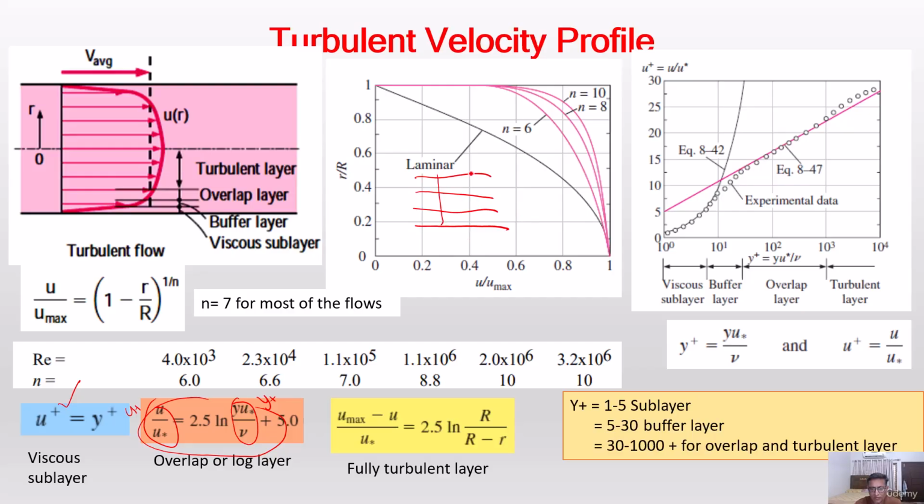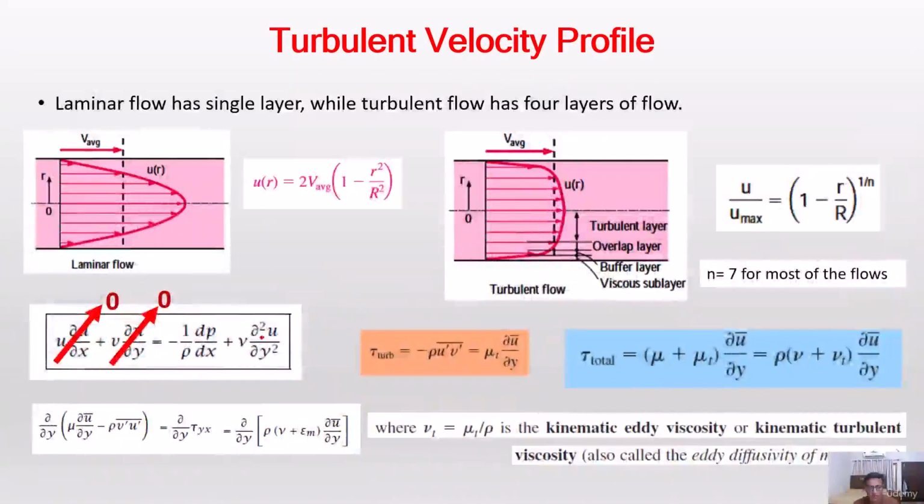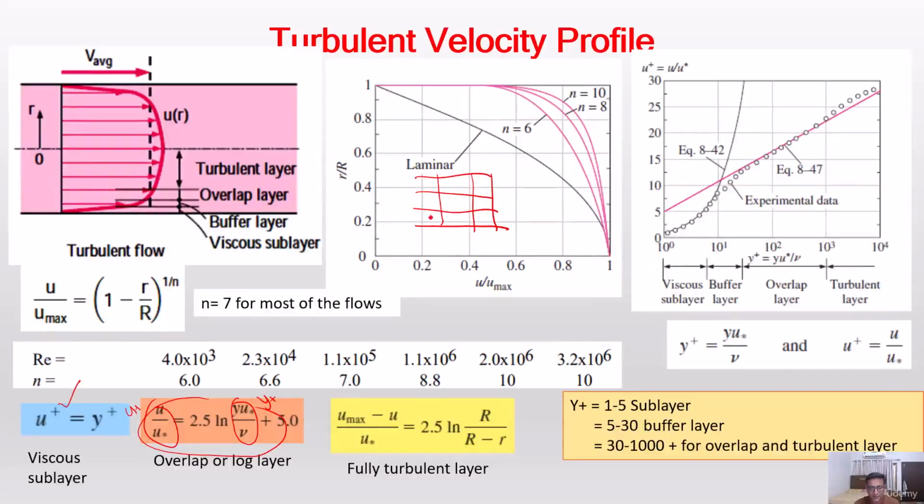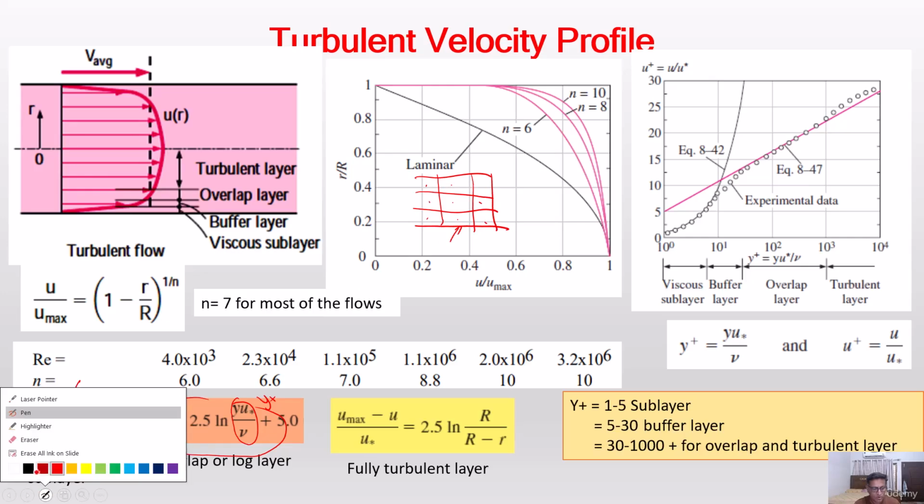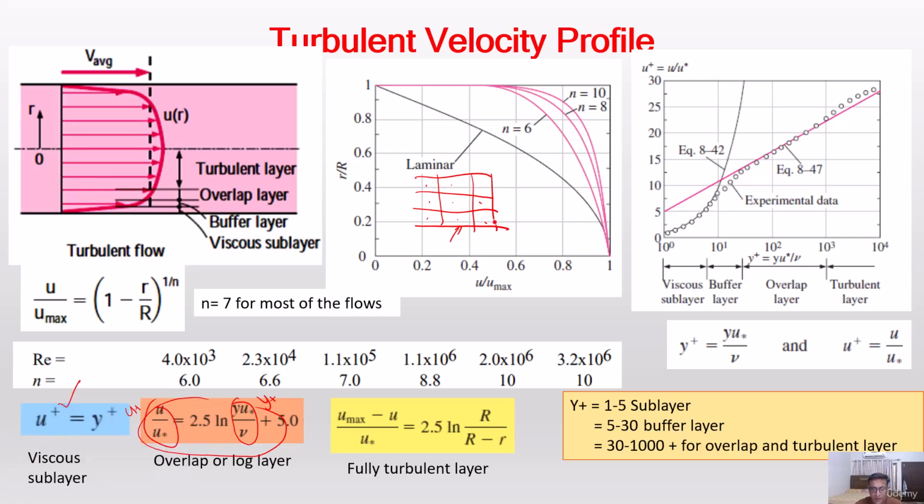So what we are doing is solving the momentum equation on these cells. If you are directly on the wall, the no-slip condition is provided from the wall. But the first cell height is not exactly on the wall. In finite difference, the first node will be on the wall. That's a different thing. In the finite volume, the first cell is not directly on the wall.